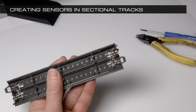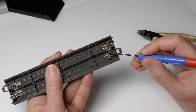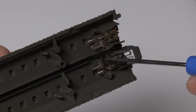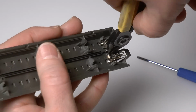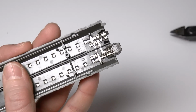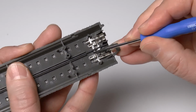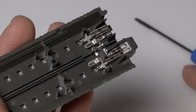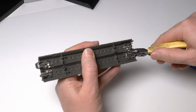However, if you have a 3-rail system like this Marklin K track, there is a bridge over between the rails here, and this one needs to be cut. Otherwise, there's no way to sense that we have a train movement on this track piece. So I'm cutting this here, and then just to be sure, I fold it away using a screwdriver. So I push it like this. And then of course we need to do the same thing with the other side, which has exactly the same setup with a crossover between the rails.